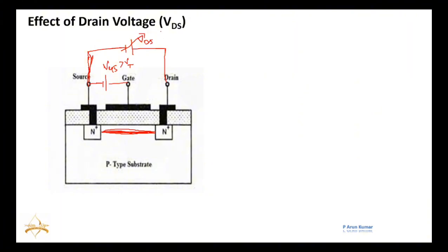And again, the same thing. We have been discussing the FET, right? If I give 3 volts here, the 3 volts will be maximum here. It is somewhere around 2, 1, and here it is 0.5 volts, something like that. So again, we are giving this 3 volts across the N and P regions, that is the reverse bias. So that is why there is a formation of depletion region because of this 3 volts. If I give 4 volts, again more depletion region will be formed.